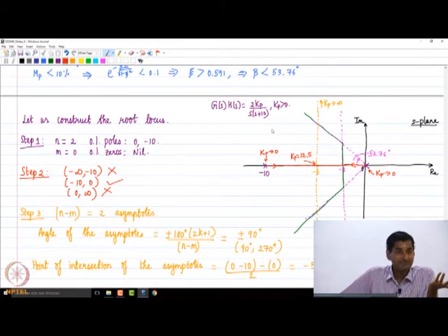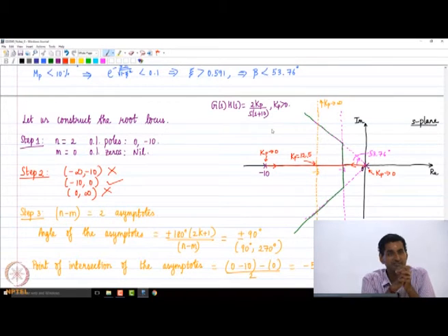It may occur, it may not occur, so it depends on the problem. If you have alternating poles and zeros, but if you have complex conjugate open loop poles, depending on the relative order of the system, the values of n and m, you may have asymptotes going on the real axis. If you have open loop zeros, certainly some of the branches will terminate at the open loop zeros as k tends to infinity. That is something we need to remember. It really depends on the problem under consideration.